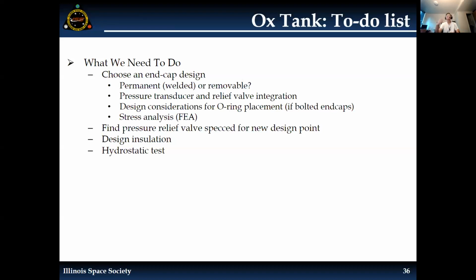Yeah, so that goes back to the 2 different pressures that I talked about earlier. One is our storage pressure, one is our design pressure, right? And the maximum allowed operating pressure is 1.5 times the design pressure, which is 76 bar. But our storage pressure is 45 bar because the vapor pressure of nitrox reaches equilibrium at 0 degrees Celsius at 45 bar, if that makes sense.